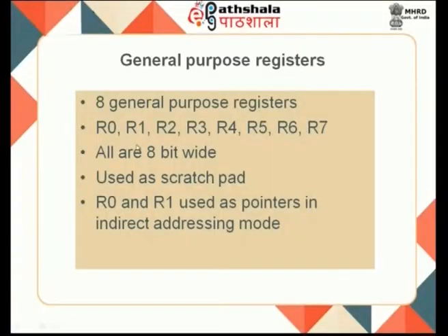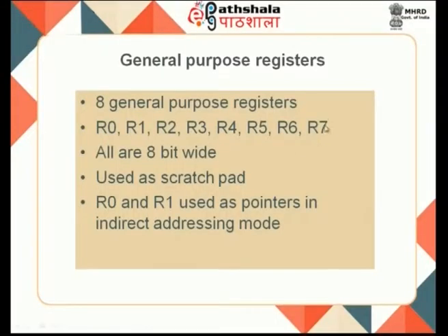Okay. So, as I told you, the general purpose registers: we have 8 general purpose registers, R0, R1, R2 up to R7, and all are 8-bit wide. These registers hold both data as well as addresses while we are processing any instructions. They are used as a scratch pad where you can move data and move addresses.